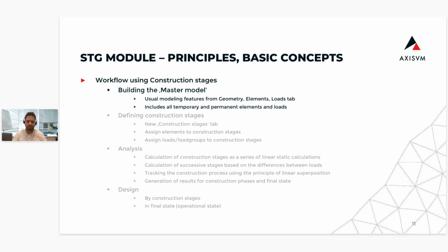So first, we will need to start a master model, which is a principle that you should take away from this webinar. What is the master model? The master model is itself a model which includes all temporary and permanent elements and loads also. That means that all supporting structures which are only present in a certain construction stage have to be presented or modeled in this master model.